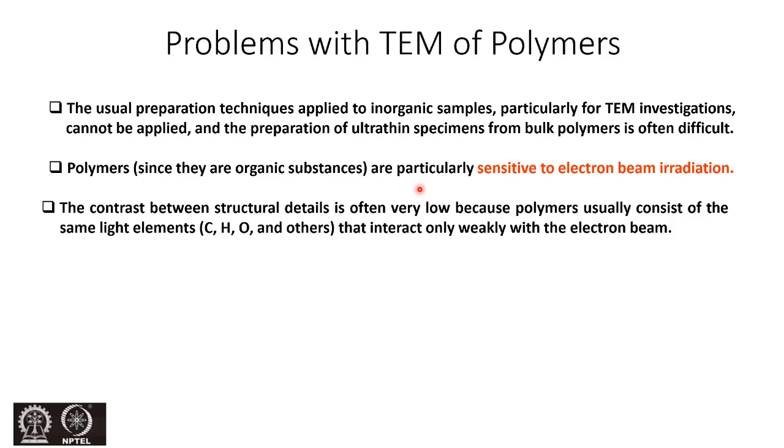Then the contrast is also very low because here we have only very low atomic weight molecules, so those will not give us very good contrast. So that's why it is kind of difficult to obtain the TEM of polymers.